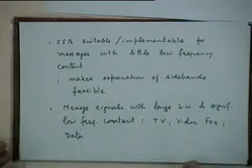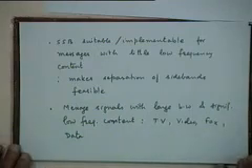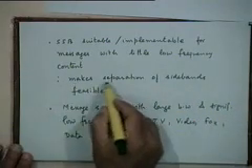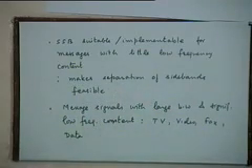All these kinds of signals, they have significant low frequency content. So this separation becomes more difficult, and if you try to enforce it, it will create all kinds of distortions which are not acceptable. Okay? And it is for such applications that one thinks of VSB.